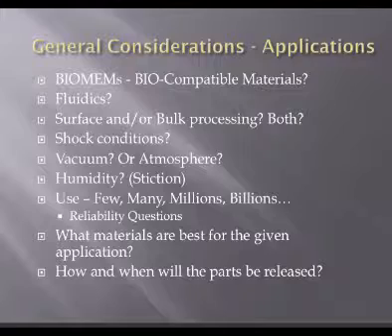That's tricky. If you release it on the wafer and then you try to cut the wafer apart, you're going to destroy the parts. If you encapsulate everything on the wafer, cut the wafer apart, and then release it, then you've got all these little parts floating around in a bath, and you have to collect them and put them together somehow or mount them on something.